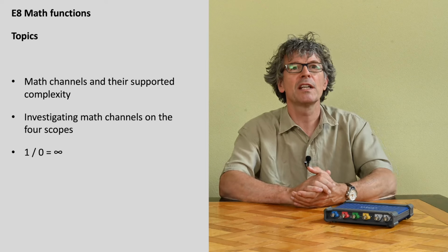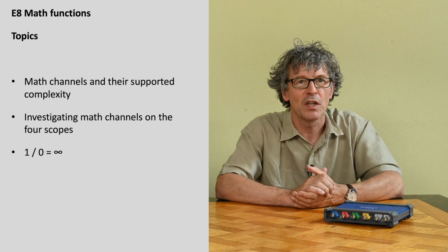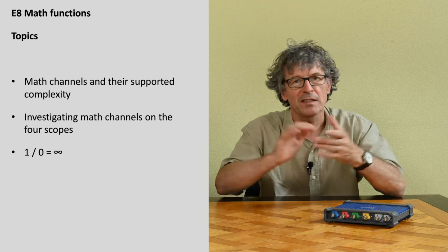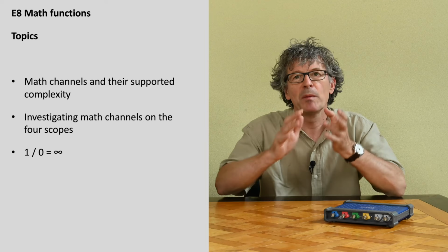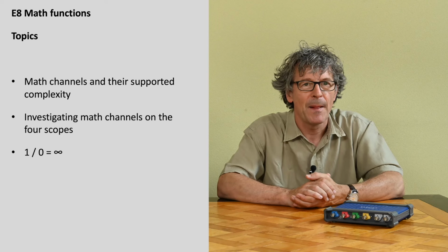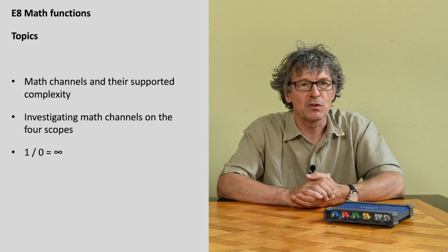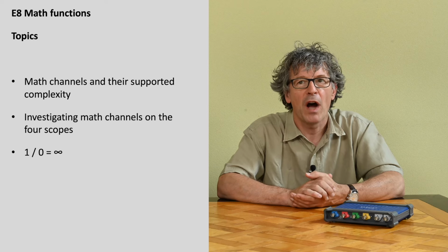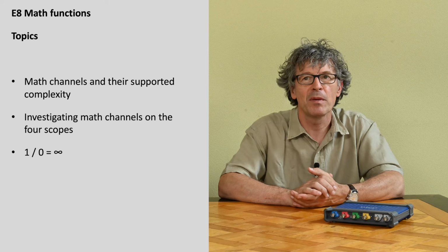There are a lot of types of tasks we face where we need to do sometimes simple and sometimes advanced mathematics. So today I want to look into the math functions of the three oscilloscopes that I've been looking at before. The topics I'm going to deal with today: first, I want to talk a bit about math channels, but also the complexity of these math channels. Then I will be investigating and testing all three devices, how they do things. And then I want to go into the question of how they deal with division by zero.